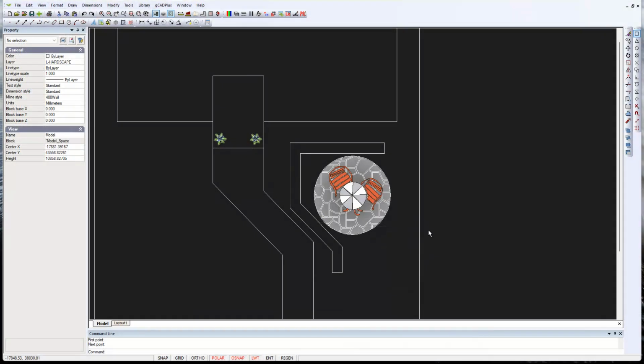Well, as I look at the design at this stage, that little dry stone retaining wall looks a bit too massive to me. Let's use the measure tool. And you remember from there to there is 400. I'd like that, and I phoned the stonemason we used, and he would be happy to do 300 wide. So we can use our modifier and offset to get that easily adjusted.